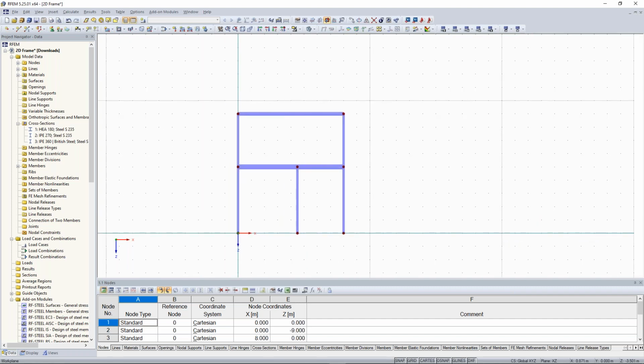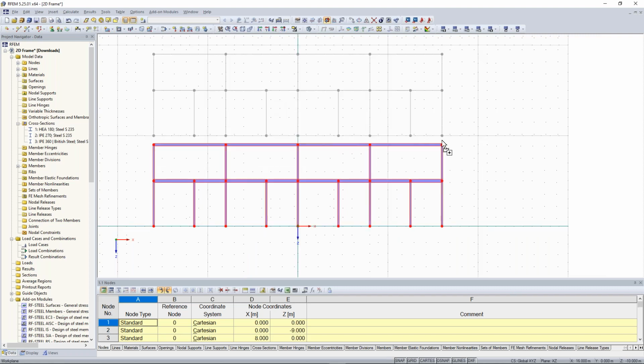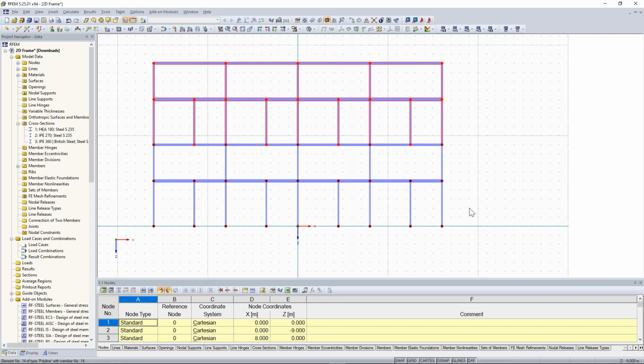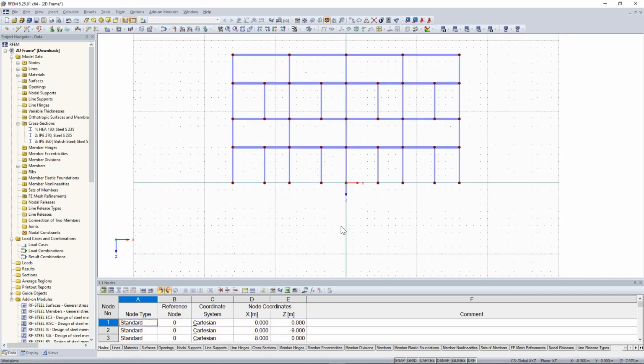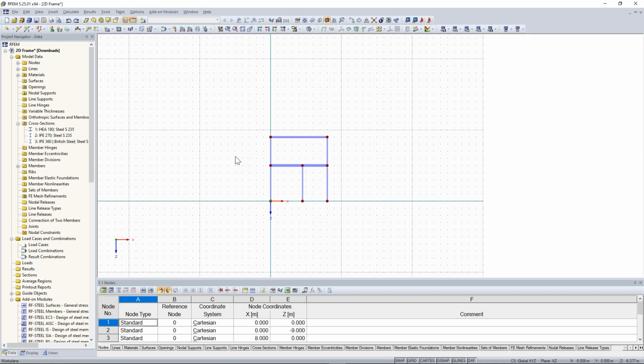Maybe I can show you the power of this function also with a great example. Just select everything here. You don't have to do it. Press the Control key. Click maybe on the left corner node, and then just easy and simple copying. It's so easy. It makes your life really easy and makes fun. Okay. I make it undo. Just click the Control key and Z, or here also in the symbol bar, the undo button. Okay.